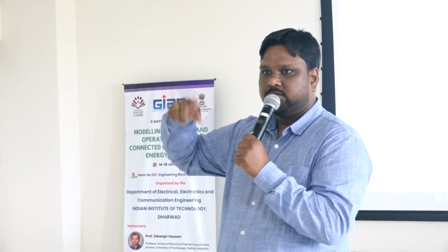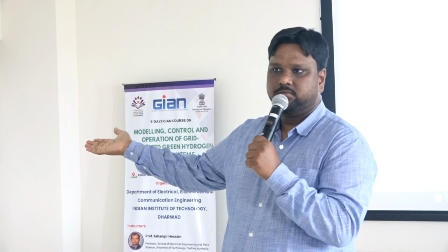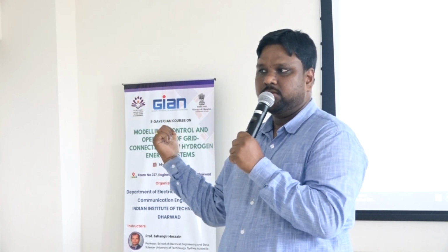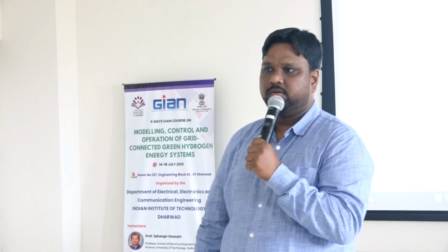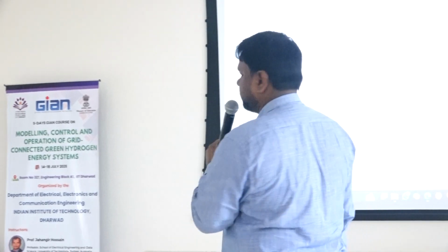The sequence I maintain for switch on and off in the primary, I maintain for the secondary also. After giving this phase shift, whatever goes to switch number 5 will go to switch number 8. And I will use the NOT gate on that and give it to 6 and 7. That is the whole story. Okay? There is a phase shift. Can you create a phase shift on that?